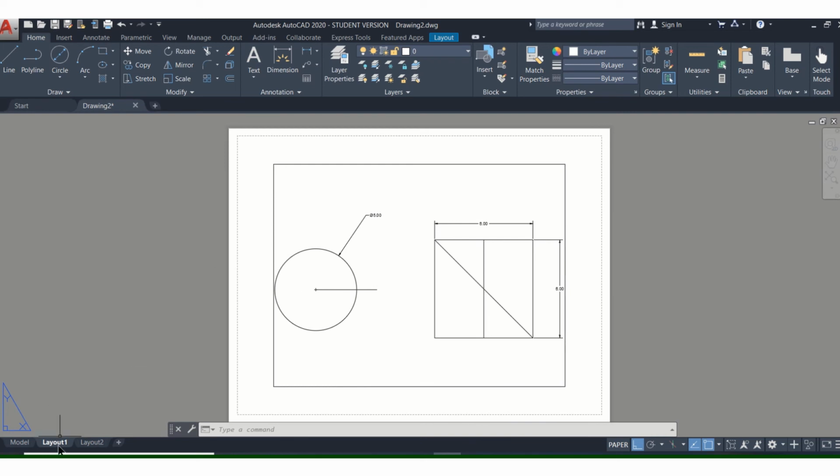So all you do is go to the layout tab. Now this is the border. You always want to have a border around your drawing. It makes it look more professional. It shows exactly the limits of your drawing. Unfortunately, the default on this template is it leaves this crazy wide border, which we don't want. So you see this dashed line. The dashed line is the limits of what can be printed on the piece of paper. The printer doesn't have the capability to print all the way up to the edge. So that's just a guideline for you.